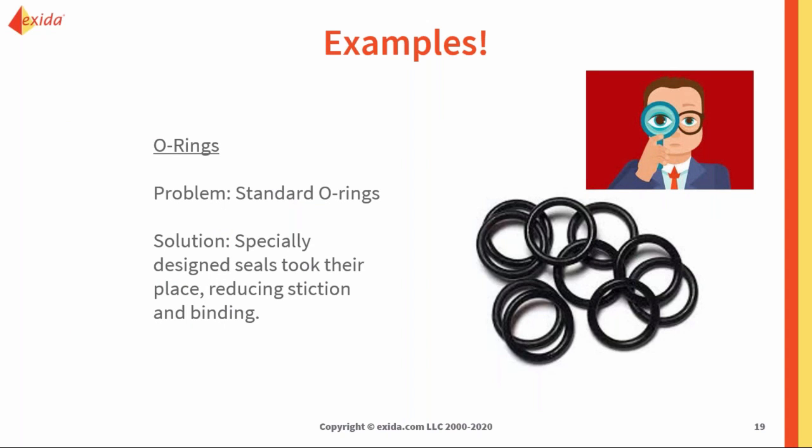Another example, and this could be on any type of device, O-rings. We know that O-rings can do a lot of funny things. They can leak, they can stick, they can bind, they can break. But we have seen specially designed O-rings that were proven in testing to have less binding or sticking than average